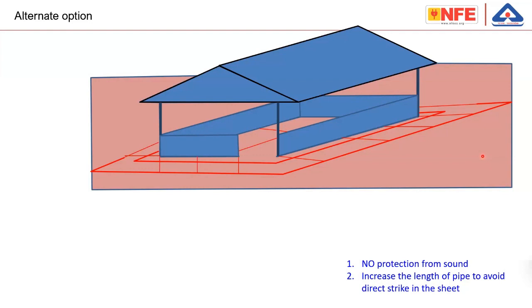It is not scientifically proven, but if required, through software we can analyze, we can simulate, and we can test whether this will work or not if there is a demand. But this can be a practical solution: a metal shed with metal supports, that means the roof is properly grounded. Then on the earth, all the metal poles are interconnected to a kind of grid all around the area, inside and outside the building, so that potential equalization is also made.